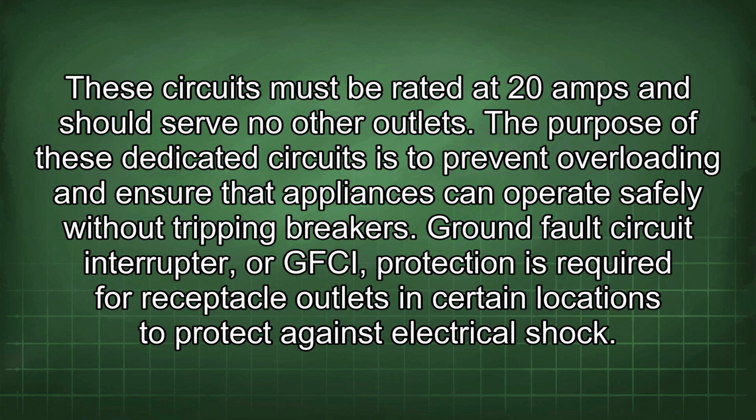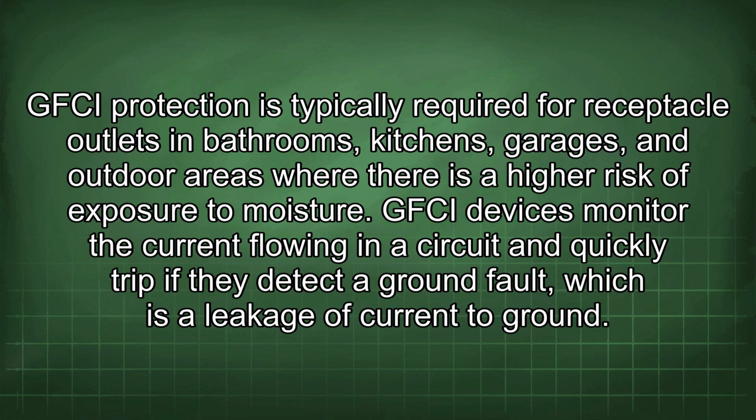Ground fault circuit interrupter, or GFCI, protection is required for receptacle outlets in certain locations to protect against electrical shock. GFCI protection is typically required for receptacle outlets in bathrooms, kitchens, garages, and outdoor areas where there is a higher risk of exposure to moisture. GFCI devices monitor the current flowing in a circuit and quickly trip if they detect a ground fault, which is a leakage of current to ground.